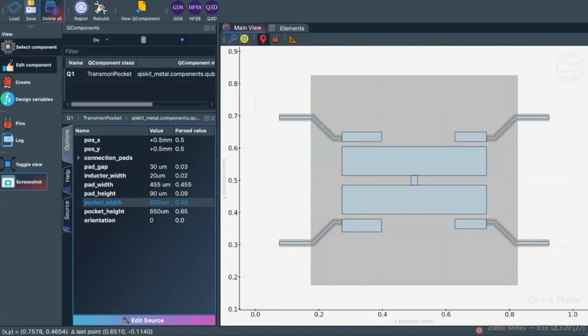Yeah, thanks, Priti. So I guess quantum dots are potentially, to a degree, similar in terms of the physical layout. They also operate on a chip, and they're more typically electrostatic based. So you can define a number of little wires, gates that can confine electrons in a very small space, in such a way that you can have only one electron or no electron, things like that. And also there's a lot of simulations there. So I think you could draw that chip and do the regular EM simulation.